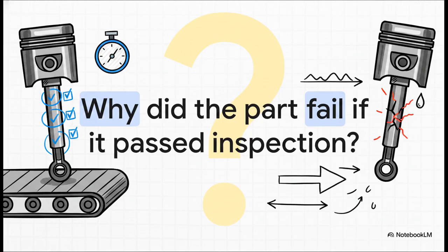But when that rod is actually put into service out in the field, it fails. It leaks, it wears completely unevenly, or maybe it even binds up. So you have to ask yourself, why did it fail if it passed inspection? Well, the answer is simple, but frustrating. The entire rotating surface wasn't uniformly controlled. The spaces between those specific cross-sections you checked had hidden variations, maybe a slight taper or a subtle wave, that a basic circular runout check just wasn't designed to catch.